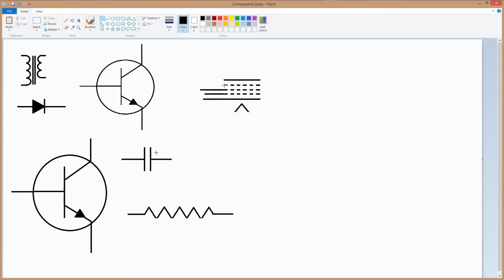And what I'm going to do is sort of unusual on this anode in that I'm going to put 2 connections out, because this is a tube that is designed to be used as a template. And so when I actually put it in the circuit, I can eliminate one or the other of the leads off the anode to suit my purpose, depending on how I'm going to connect to it. So this is a template that I can modify once it gets into the drawing.